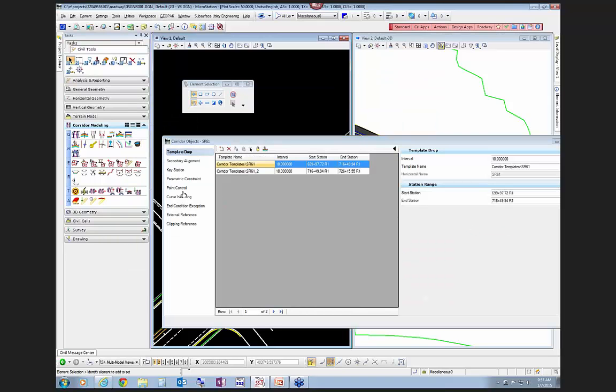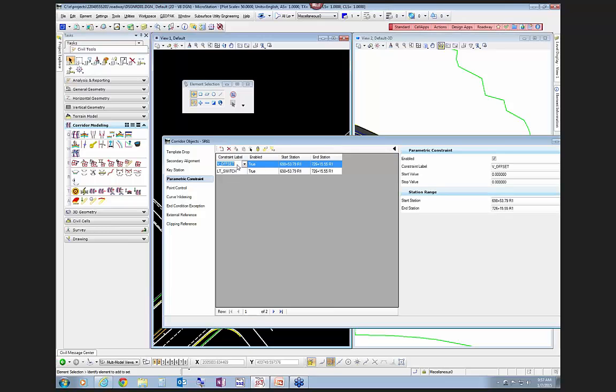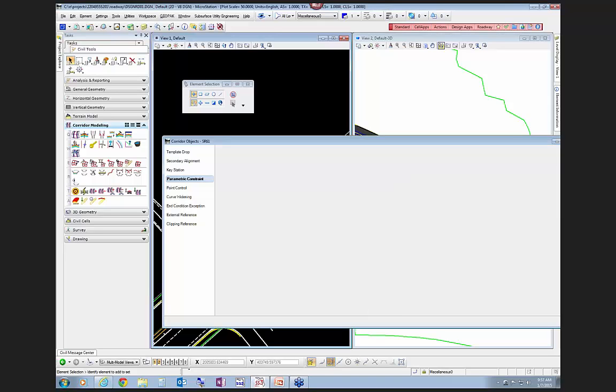See, I have this vertical offset switch that's set to 0. That's what puts everything down so that everything ties together. And then I was using this left switch, and I was setting the value to turn on and off the intersection, was what I was attempting to do. So that's another way of controlling your outside end conditions.